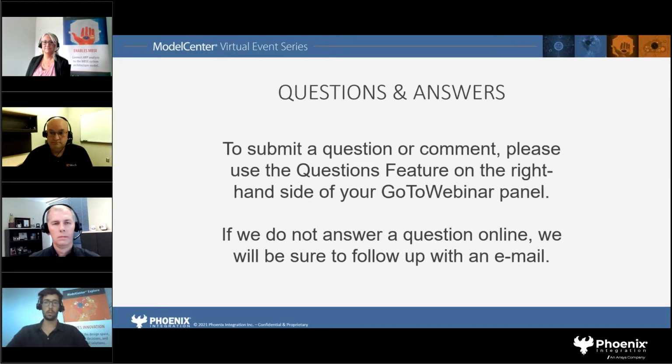When you fire up Model Center MBSE, I've been a bit quick on that during the video, but you have the possibility to export the requirements and constraint definitions created in the system model. It will create simple scripts that will be saved in the analysis path. And when you fire up Model Center MBSE, they will appear in the list of analyses that are available.